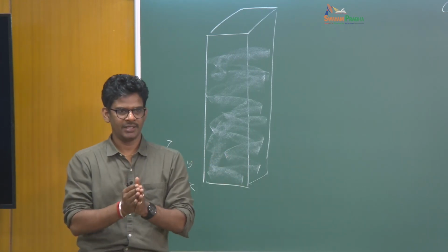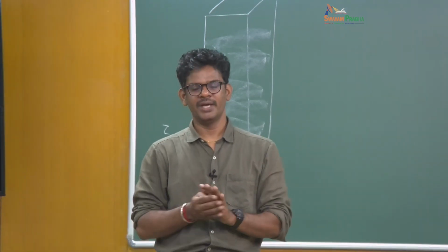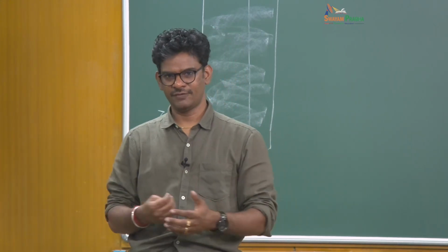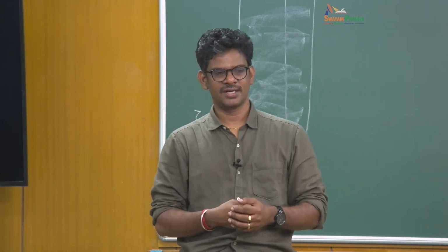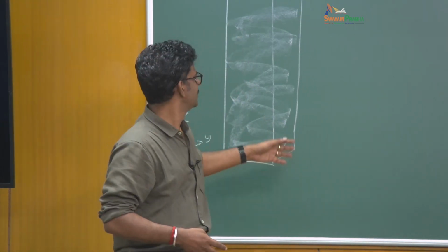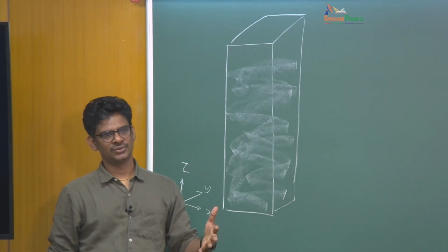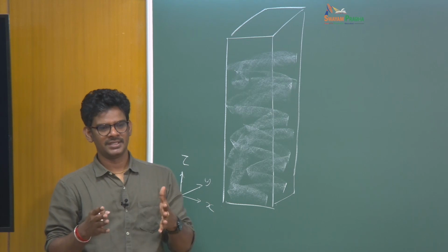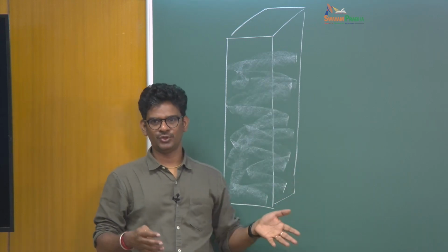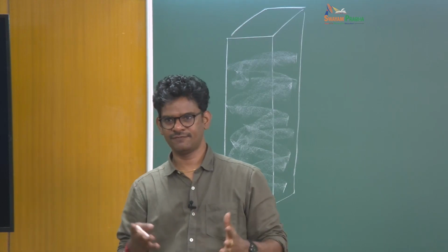There is another domain in which the particles are neither too small nor too large, where there is sufficient Brownian motion, and at the same time the particles are subjected to a gravitational field. In this case, the concentration profile will not be uniform. It will not phase separate. You will get an equilibrium distribution based on a certain profile. So our task here is to look at the problem of a Brownian particle in a gravitational field. What is the equilibrium distribution of the particles? This is directly applicable to chemical engineering, as I said, sedimentation, floating, etc.